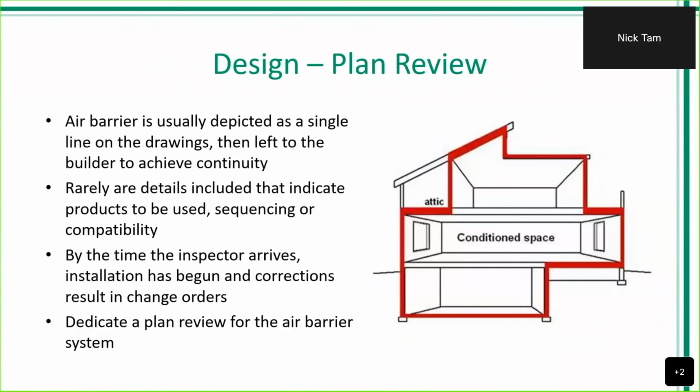And so when we go through the design and install process step by step, we start with the process of drawing the air barrier. The saying goes that the designer should be able to trace an air barrier around the entire circumference of the building, especially the entire area that's encapsulating the conditioned space. That is important, but proper detailing is also necessary.